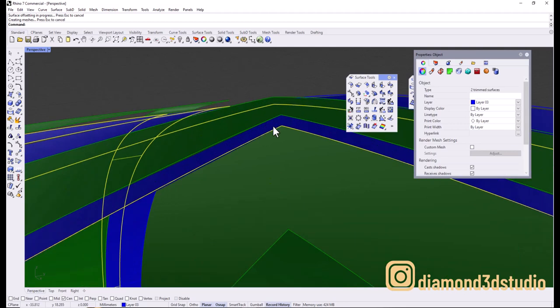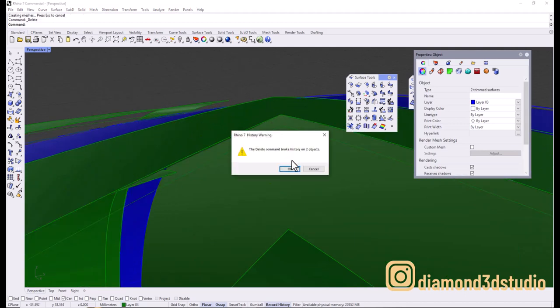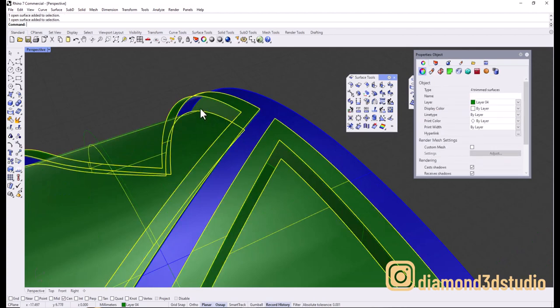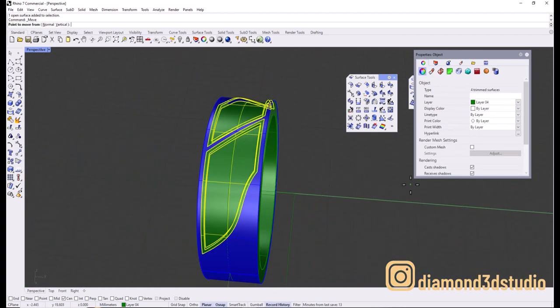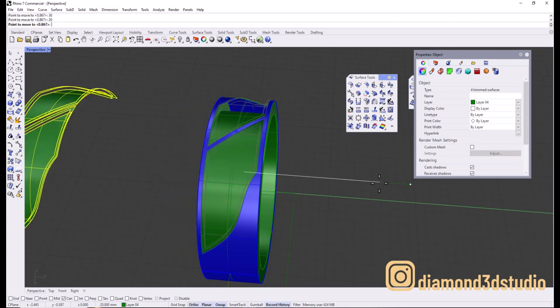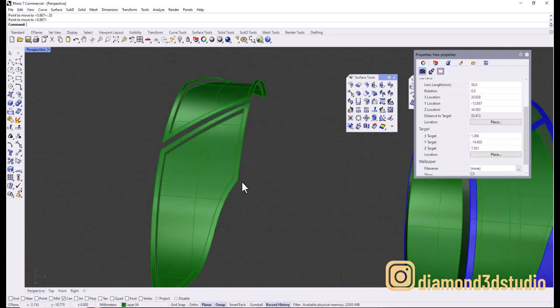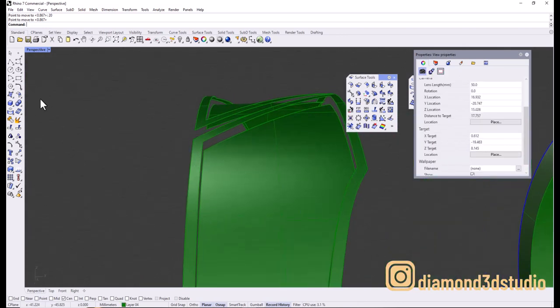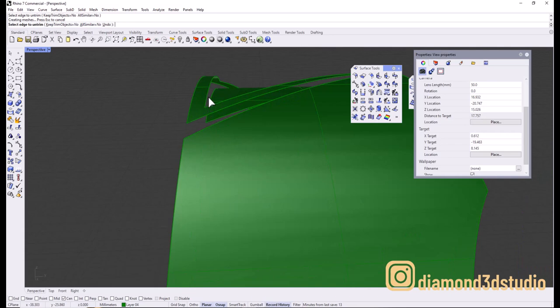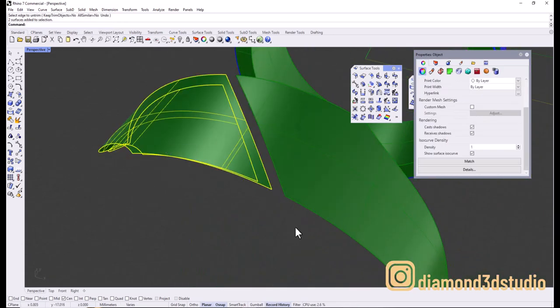Okay, and the same thing, I want to get rid of this surface too, so I don't need those two surfaces as well. So just to make things easier, I'm going to move these four surfaces aside so we know exactly what's going on. Okay, so I've moved them around 20 mm away, and I'm going to use the untrim option over here, and I'm going to do the untrim option over here as well. Make sure the all similar is no. Okay, and then you select these both together,